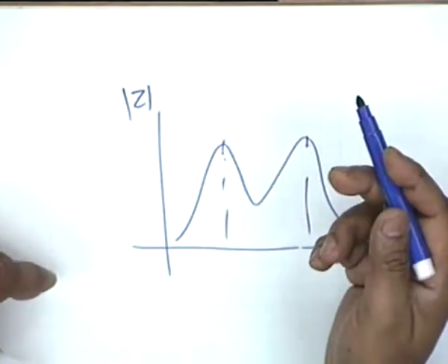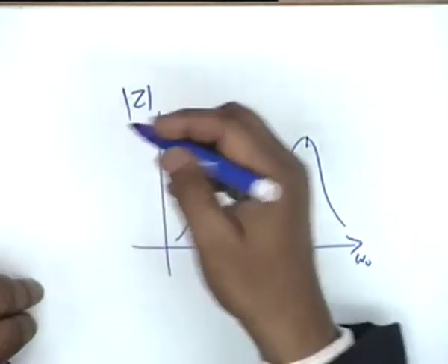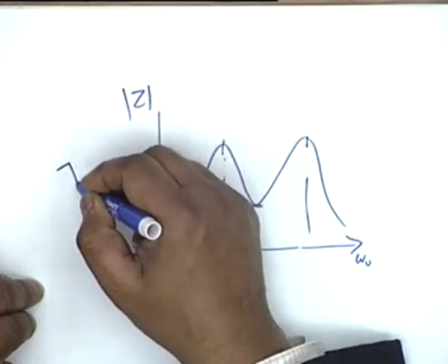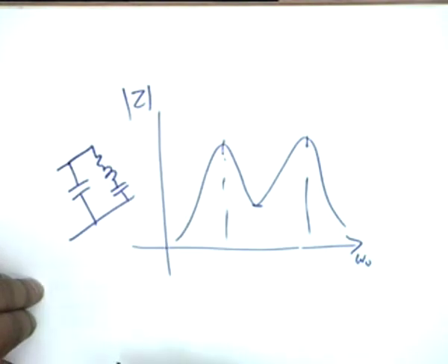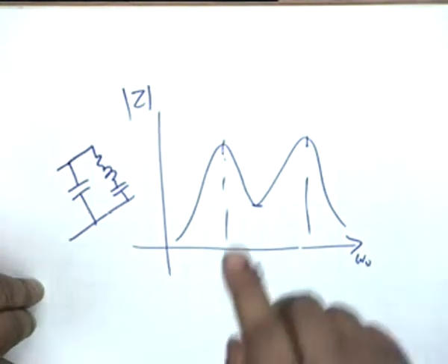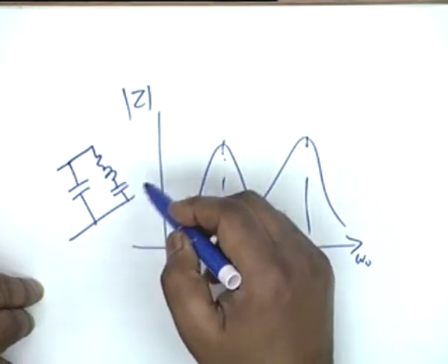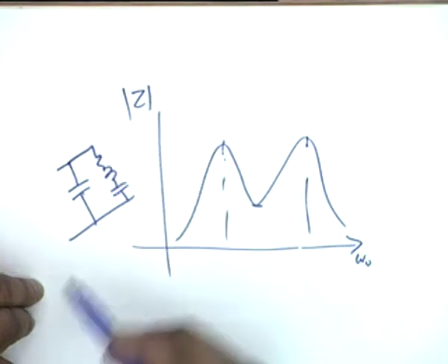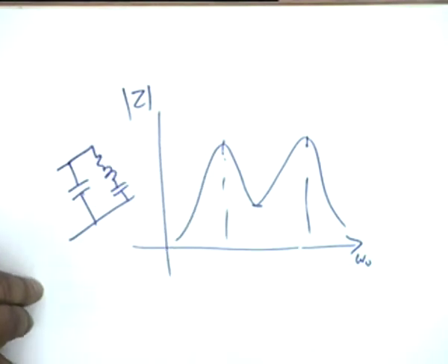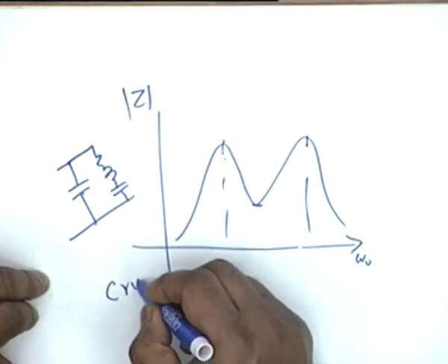Parallel. In parallel resonance, the impedance maximizes, admittance minimizes, and this can be considered as due to a series resonance. And a simple circuit that one can think about is the following: a capacitor shunting a series resonance circuit, RLC. There will be a series resonance in this, and there will be a parallel resonance also, because the capacitor is shunting a reactive element.